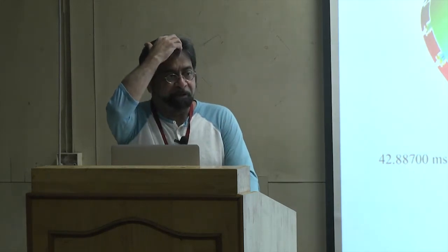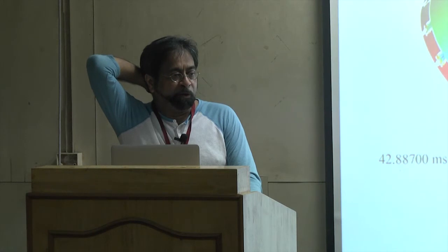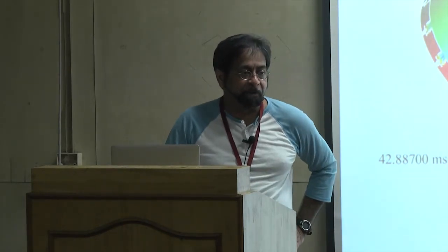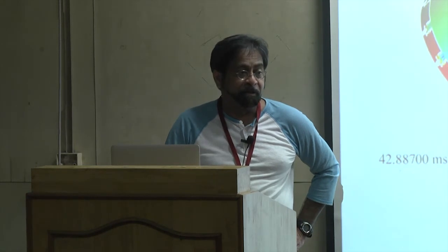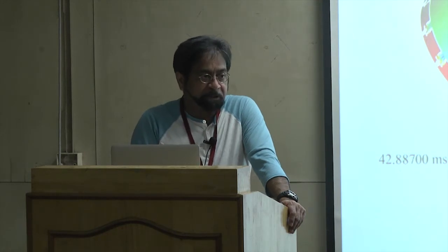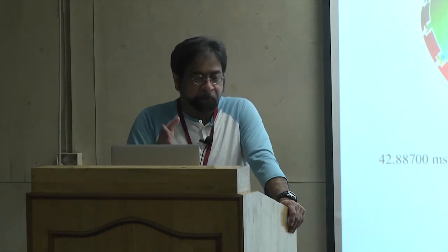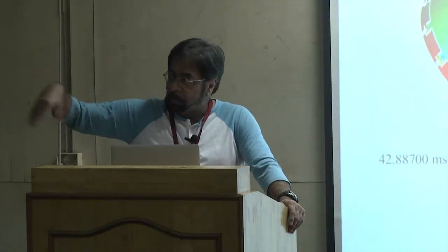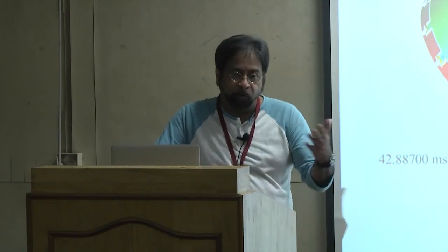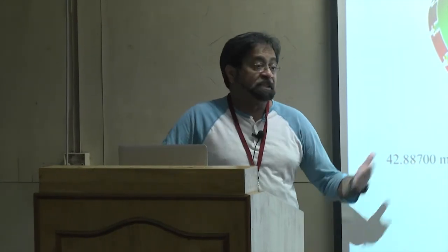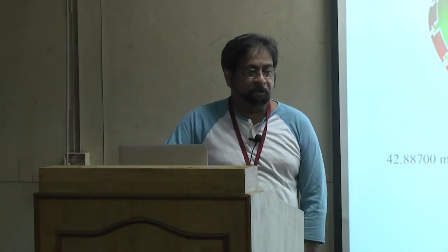So how much knowledge you need becomes questionable. When you simplify, you're losing something, right? So the question is, can you live with a low frequency, just standard transfer functions, or do we need to put in a time dependent transfer function? That becomes the problem. I don't have an answer on which is the best solution, because I can post process from these simulations and give you a transfer function and impedance, and it's varying all over the place. You'll have a mean value and a different frequency, but you'll have a lot of structure to it. So the only way to do it would be for somebody to run different structures of the impedance and see if the results are sensitive, but that's a big effort in itself.